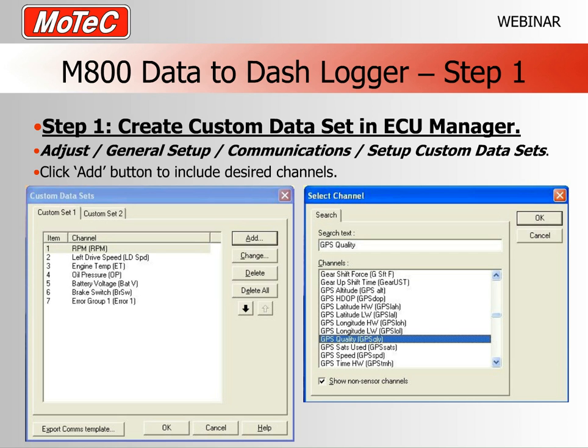So the first thing we need to do to get M800 data into a dash logger is to create our custom data set in the ECU Manager program. So we do this by opening the ECU Manager program, and then we go through our menu structure, which is Adjust, and then we select our General Setup, our Communications, and we click on Set Up Custom Data Sets.